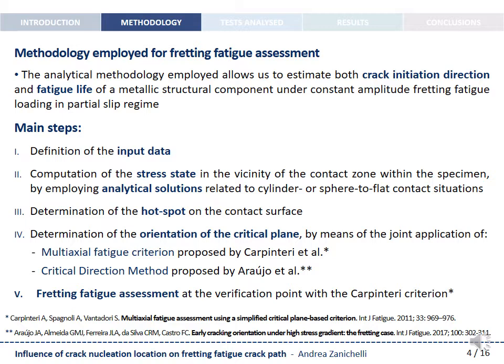The first step consists in the definition of the input data. Then the stress state in the vicinity of the contact zone is computed within the specimen by employing analytical solutions related to cylinder to flat or sphere to flat contact situations.